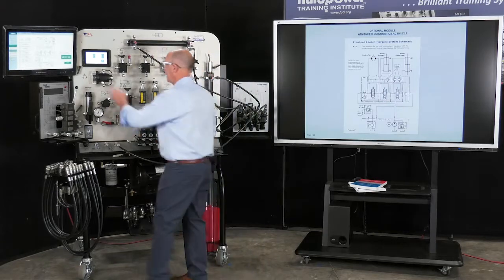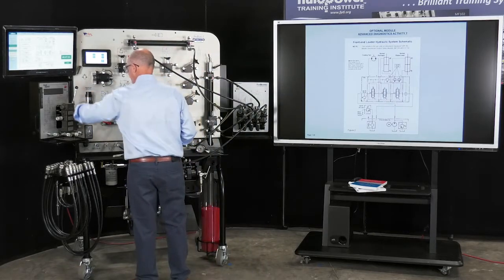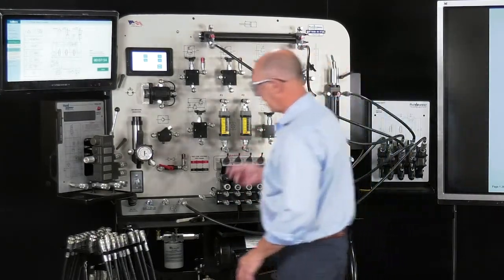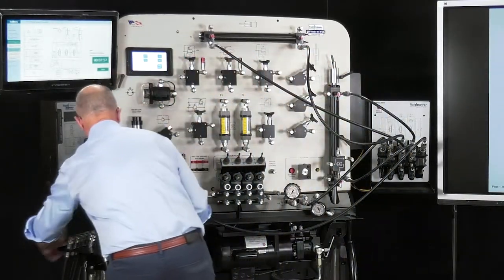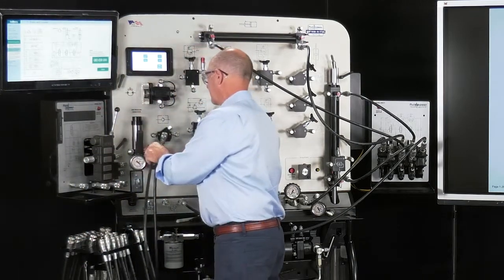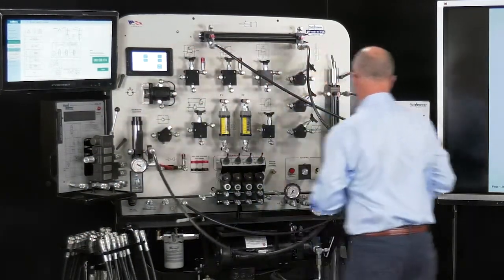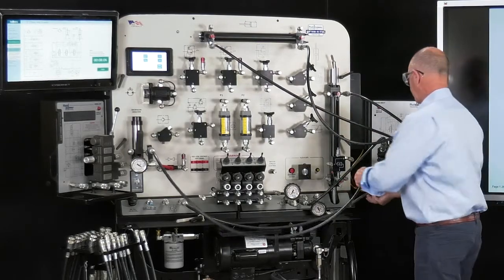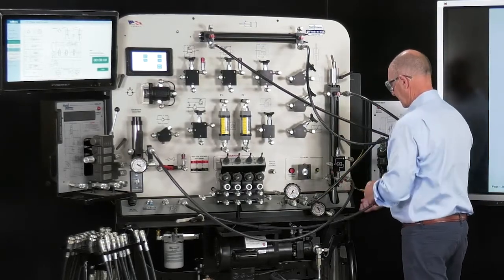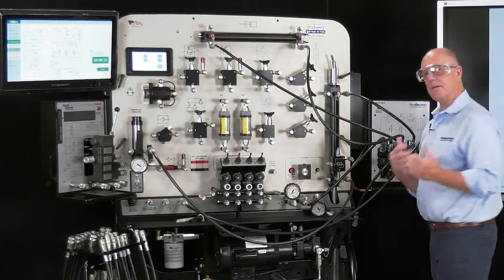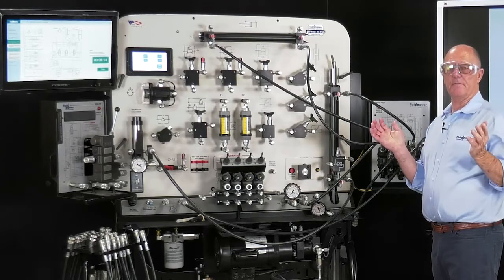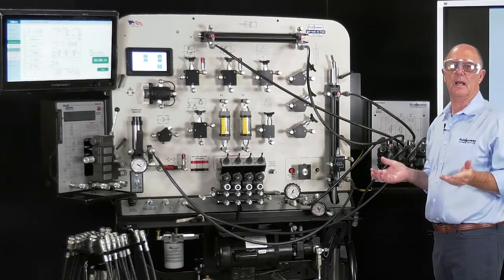So now I'm going to take a transmission line from the microleak tester and go to the bottom port of the cylinder. Okay, so let's go to the bottom port of the cylinder. Now, in the field, I would take the line off the top. Just take it off. Remember, it's safe because nothing's running. This machine is shut down.